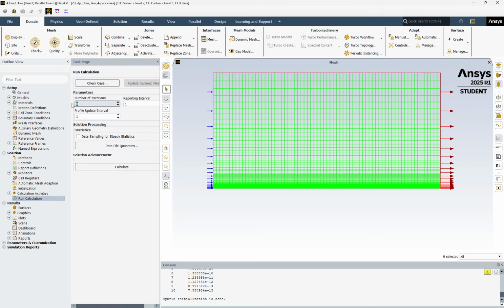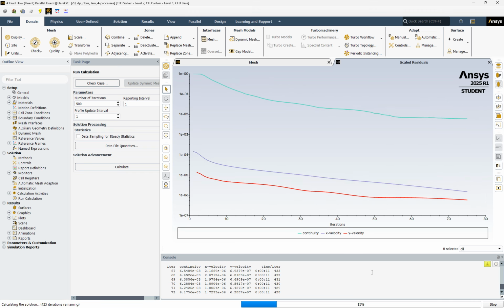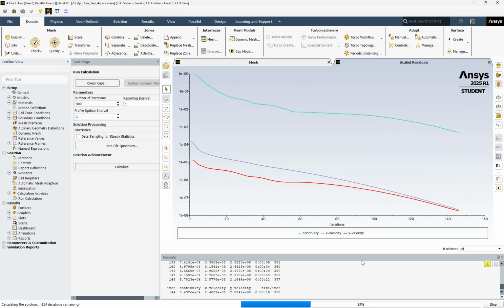What we're going to do is basically 500 iterations. The initial guess is needed in order to calculate and solve this set of differential equations. You need to start with something and solve the governing equations iteratively. You will see later that the values that you use may, in fact, help the convergence of the code, or if your guesses are too wild or they do not make sense, you may run into trouble.